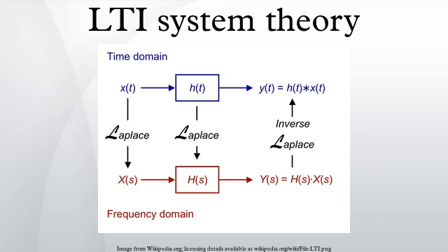Impulse response and convolution. Let x[n] represent the sequence, and let the shorter notation x represent it. A discrete system transforms an input sequence into an output sequence. In general, every element of the output can depend on every element of the input. Representing the transformation operator by T, we can write y=T(x). Note that unless the transform itself changes with n, the output sequence is just constant, and the system is uninteresting. In a typical system, y[n] depends most heavily on the elements of x whose indices are near n.